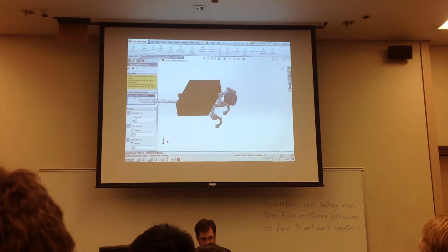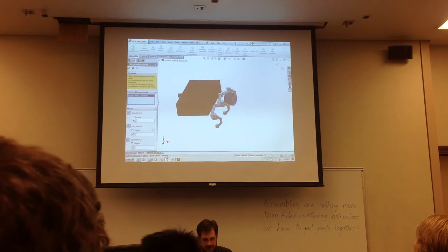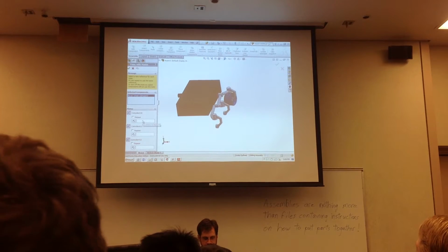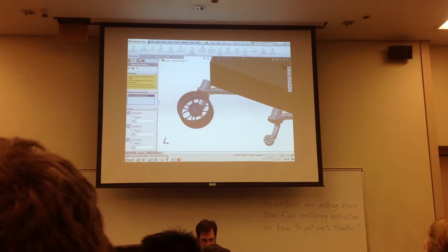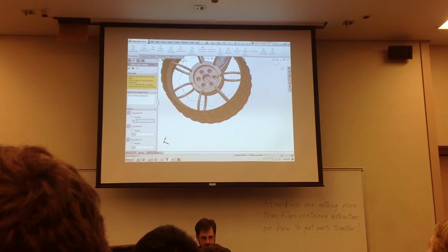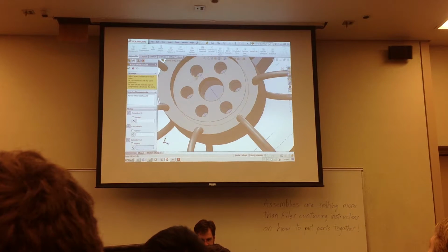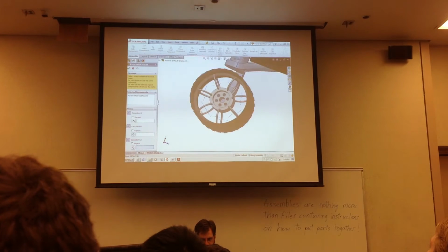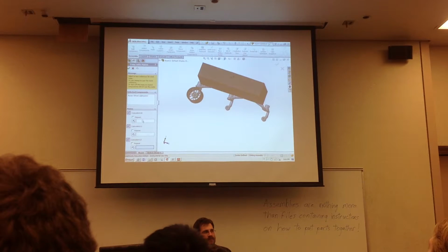First, I'm going to choose the component I want to copy, and that is the rover wheel. And the mates that I used for the first rover wheel are already listed here. So here's mating those 2, mating that hub surface, and then mating the central axes, and mating the axis and the bolt holes. Okay. So those mates are already halfway defined.